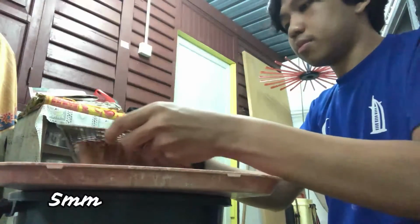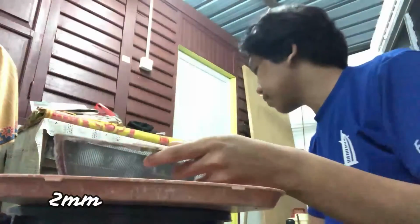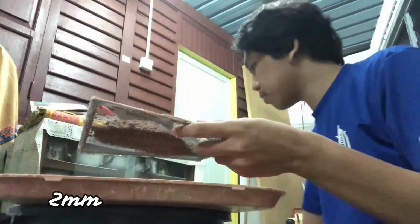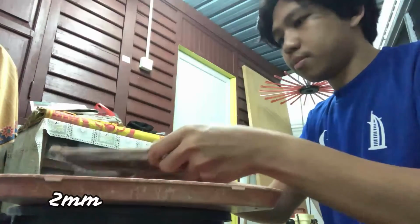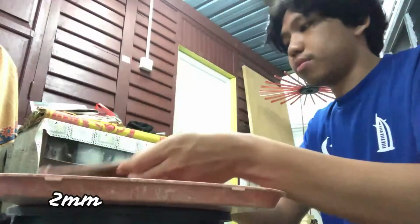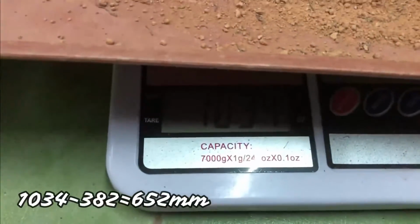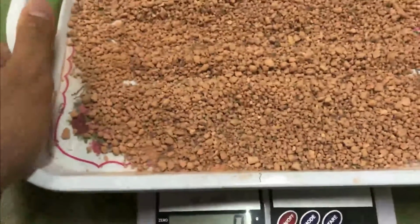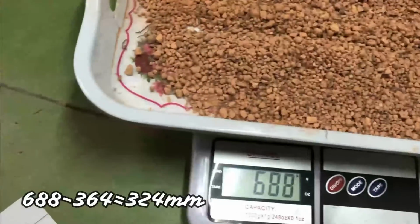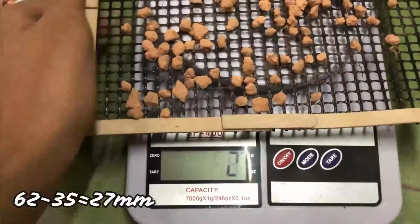There is some soil retained on the sieve. Next, I will use the 2mm sieve. There is a big amount of soil retained on the sieve. Now I will weigh the soil that is on the base pan. The soil that was retained on the 2mm sieve. Lastly, the soil that was retained on the 5mm sieve.